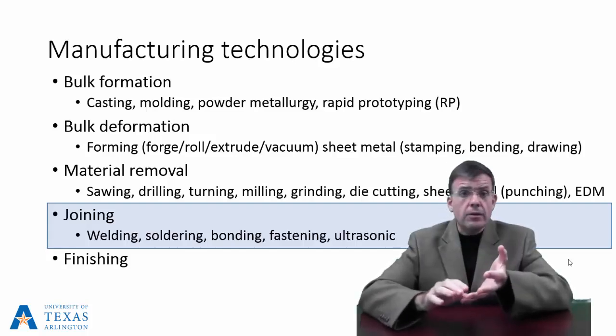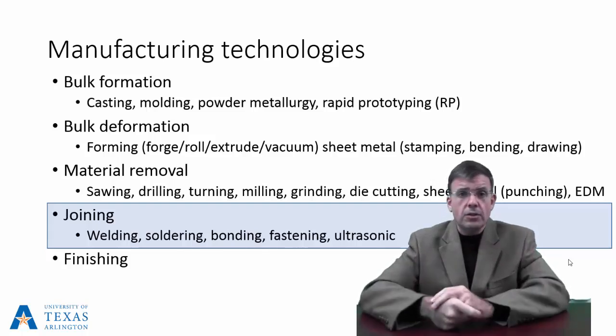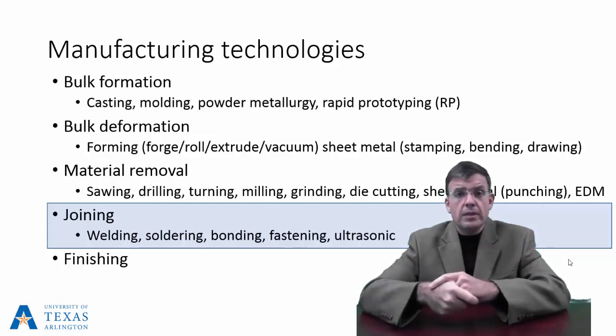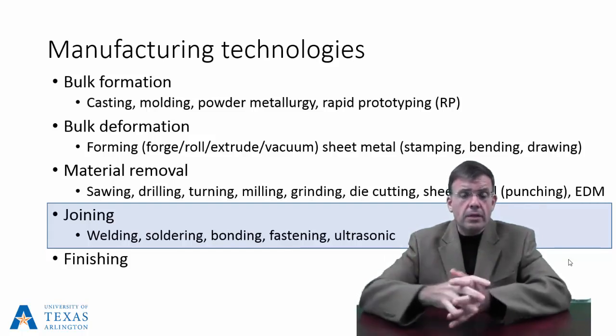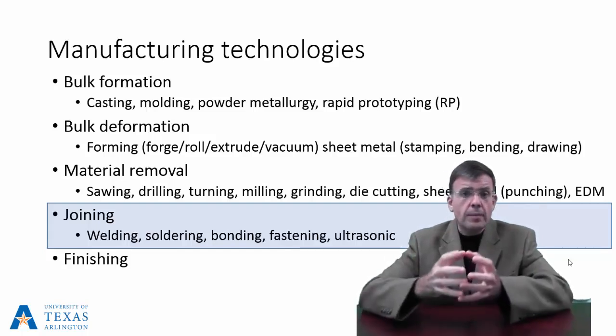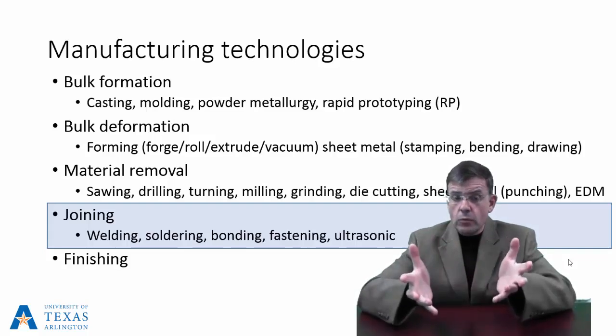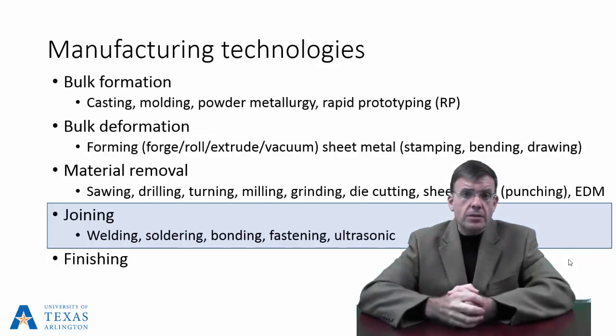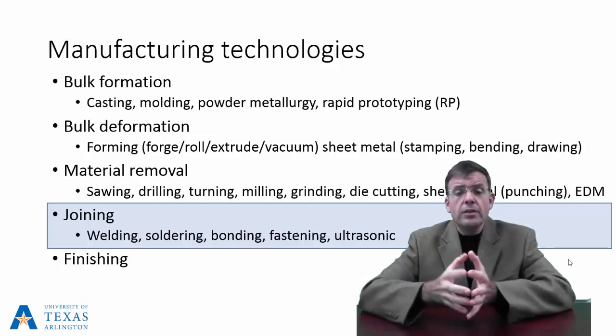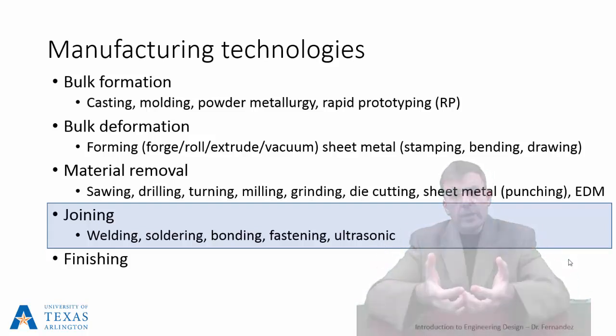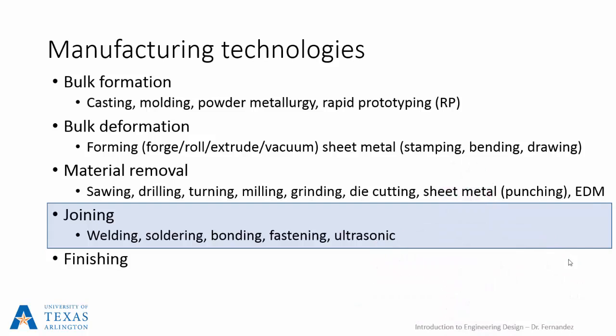You could have stick welding, you can have wire welding or MIG welding as it's known. You can have TIG welding, with or without a filler metal. You can talk about even friction welding and even other categories. Oxyacetylene welding is another technology that is used. And of course, all this amounts to heating the 2 materials so that joining occurs at the base crystalline structure.